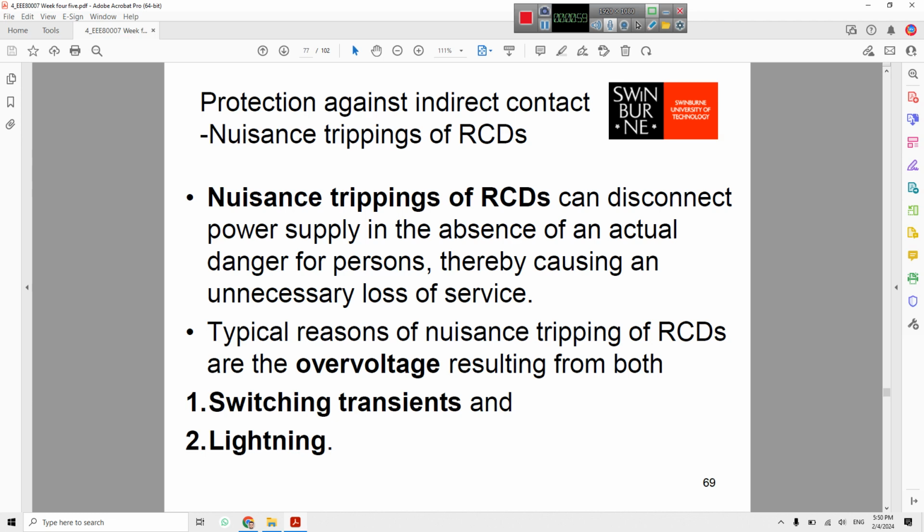So switching transients, such as the motor switching inrush current, or transients of transformer switching, which contain the second harmonic, and motors containing the third harmonic, will affect the RCD operation. So in the case of home and end users, customer applications, meaning small ones, there is no significant problem for the RCDs except for those affected by harmonics.